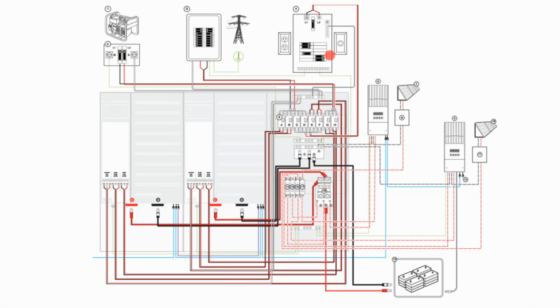That's something you can consider when you're planning even a commercial project: if we want to take advantage of the backup capabilities of our battery system, that will involve rewiring a panel into a critical load panel separate from your main service panel. Otherwise, you have to do a system that is capable of supplying the entire building.